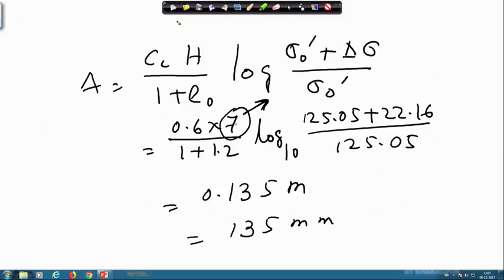This is a very practical problem, because in any foundation design, first how much pressure to be given has to be designed, and then at that much pressure applied, how much settlement it will undergo has to be estimated, because in the code we have some restriction, that means you are not allowed to settle more than a certain value, that is a recommendation. So, you have to see that the value comes out below the recommended or restricted value given in the code. So, that is another important step to check in the design.